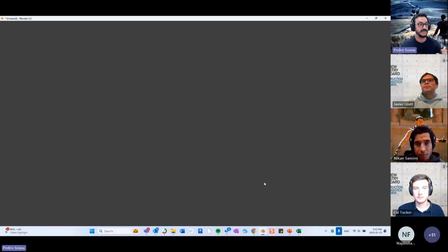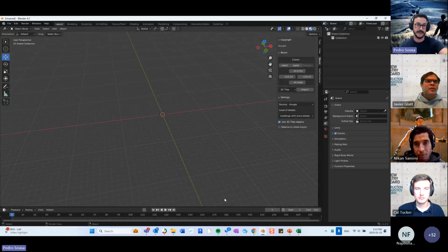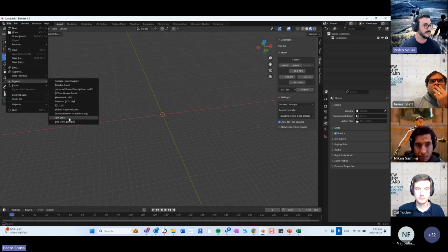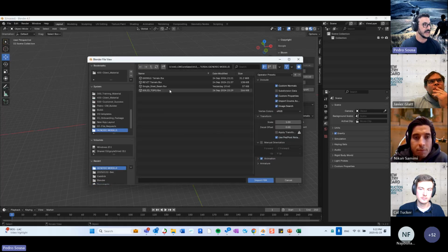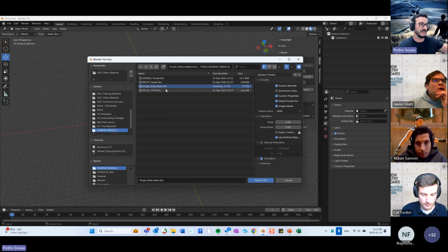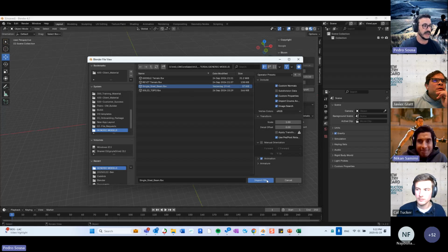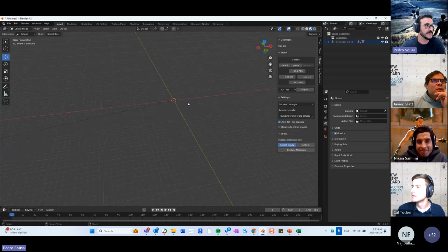But if you have a file that is a Revit file that has prefabricated parts and so on, what you can do is bring that file inside Navisworks and then export to FBX, right? Blender is compatible with FBX, so you can import FBX parts, right? So you can use Navisworks as your intermediate process to convert things to FBX. So basically, what I'm going to do is go over here to FBX, take a file that was created in Revit, convert it to FBX using Navisworks, and then import that file in here. That file will show up somewhere, right?